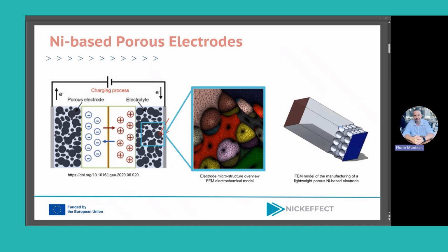Electroplating can be a good option for providing the nickel-based layer of porous electrodes. Plating processes have the main advantage of not being limited to line of sight, as for example the physical vapor deposition method. Nevertheless, the drawing power of an electroplating bath has its limits, which are not only related to the depth in the porous structure that can be reached, but also impact the uniformity of current density and deposit thickness.